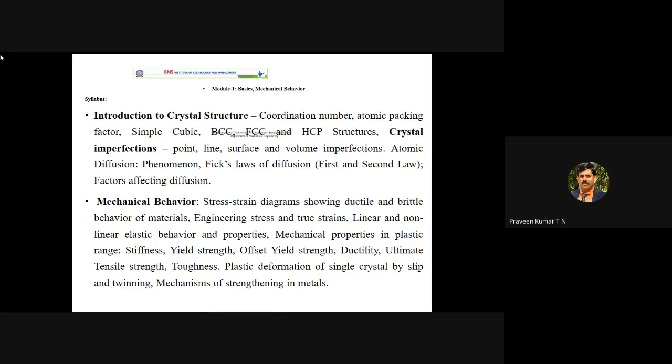But when you consider true strain, it is the change in length divided by the length of the specimen at that particular moment. Imagine you find the initial length of the rubber band. That is the original length. For engineering strain, the change in dimension is divided by the original length, and the denominator remains the same.